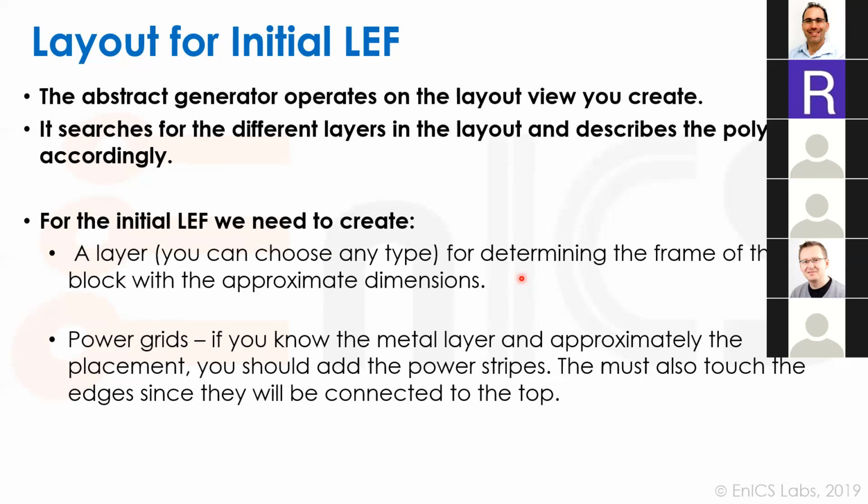So what we need for the initial LEF, as I mentioned, Slava needs to know just the size. He needs to know approximately how big our block is. And the power grids, because the power grids are the things that he integrates, and we need to connect the power grids to our block. So actually, there is one more thing, but it becomes less relevant in more advanced nodes.